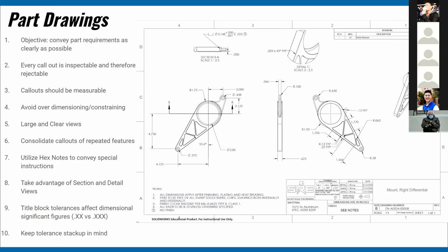So you have to be careful with your tolerances, because if the feature is not important, you shouldn't be adding more tolerance to it. Otherwise, you're making your machinist's life harder, you're making the cost of the part higher, and it's just not good for an engineering drawing. You want to reduce costs. Got it, thank you.